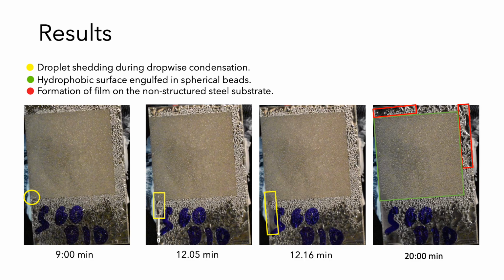Dropwise condensation was displayed as the dominant mode of condensation on the hydrophobic surface. The entire process of this phenomenon was captured during the experiment. Highlighted by the yellow marker, a bead of water can be seen to coalesce with neighboring beads, causing it to grow in both size and weight. This process would continue until the droplet would eventually advance downwards, combining with all the static droplets in its trail. This left behind an exposed area where the cycle can once again be repeated.